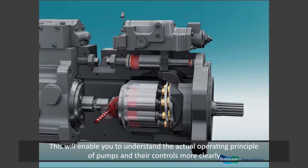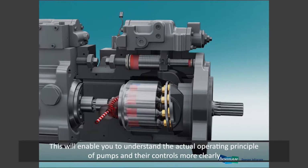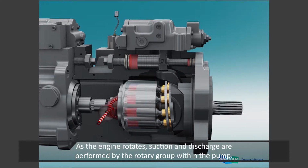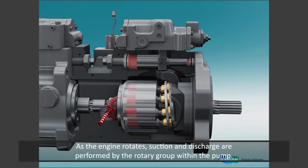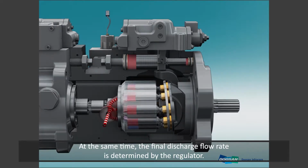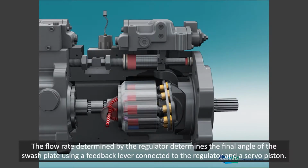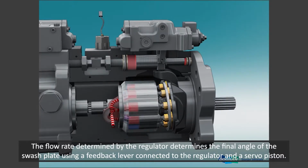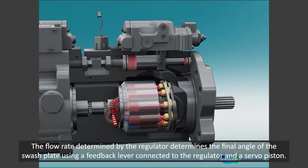As the engine rotates, suction and discharge are performed by the rotary group within the pump. At the same time, the final discharge flow rate is determined by the regulator. The flow rate determined by the regulator determines the final angle of the swash plate using a feedback lever connected to the regulator and a servo piston.